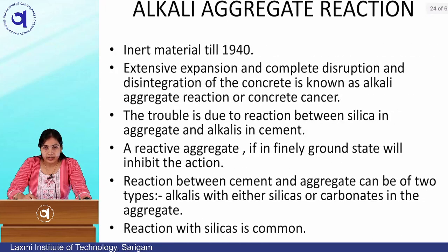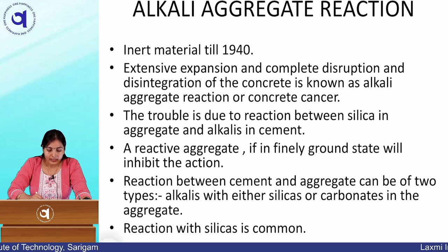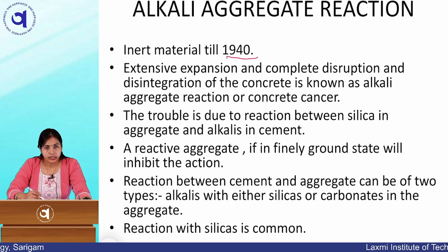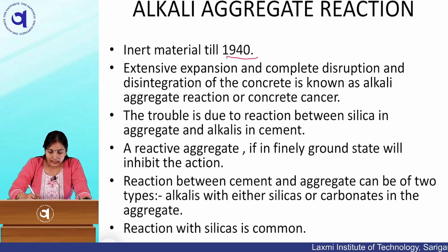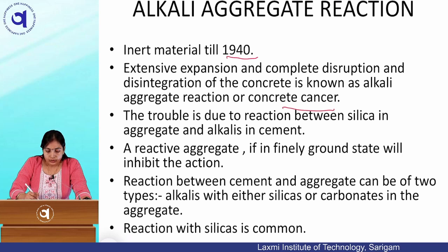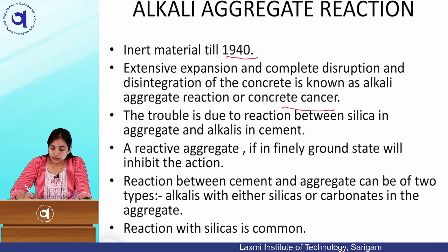Alkali aggregate reaction: we have talked earlier that till 1940 aggregate was considered an inert material, but after that we have seen certain expansion and chemical reaction in it, leading to disintegration of concrete. This alkali aggregate reaction is also called concrete cancer. This trouble is due to reaction between silica in the aggregate and alkali in cement.